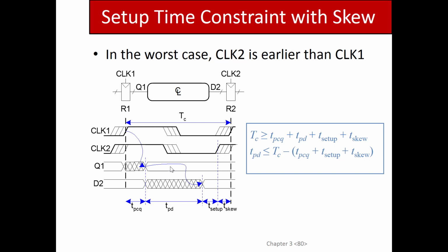Now, how much can you overclock it? Unclear. Also, aging effects. I forgot about that too. These circuits also age, and they get slower with age. Age is caused by electromigration, which is the degradation of the substrate of the chip. So the tools consider all those things. As a user, you're like, yeah, I can always add a little bit more to this. Tools say 200 megahertz, I can probably run it at 225, maybe 250. But you're taking a risk.